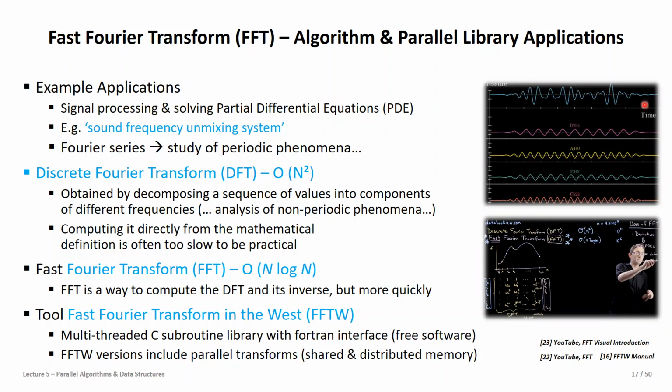Now, the interesting thing is that you could do something one could call a sound frequency unmixing with the DFT, right? With the fast Fourier transform in order to derive and get the original signals back, which is quite interesting. One application scenario is also if you have, let's say, one of them that would be very annoying, you can actually filter that out.